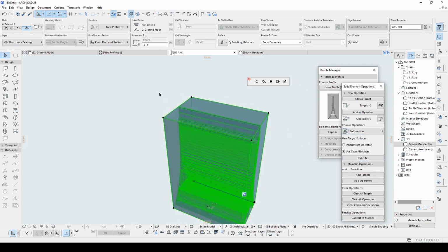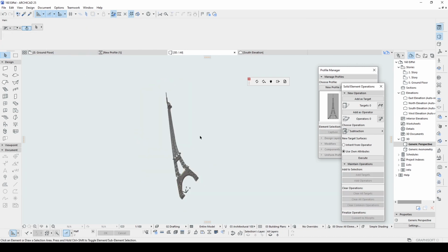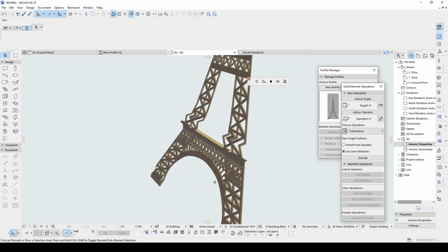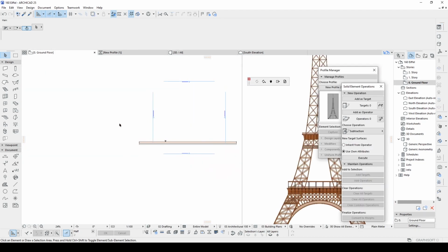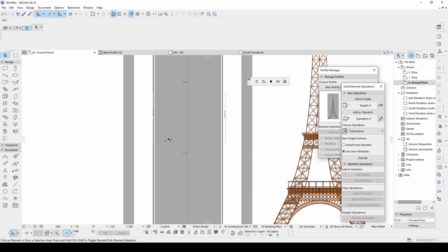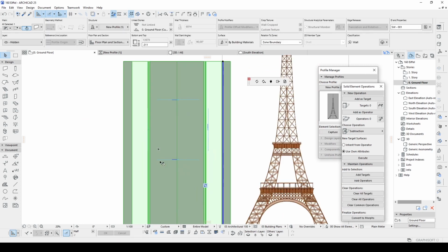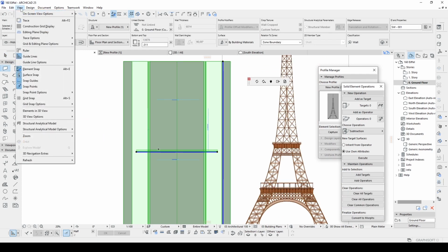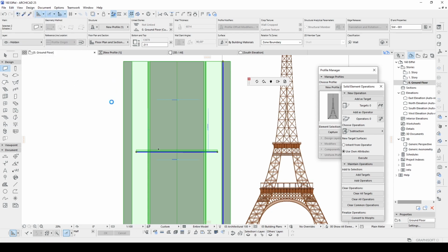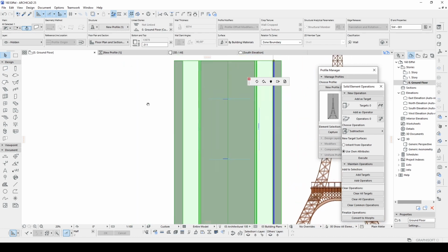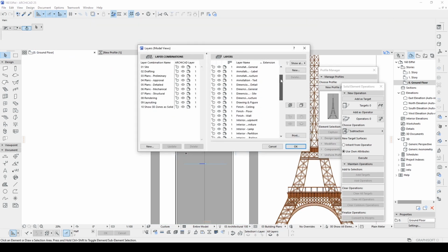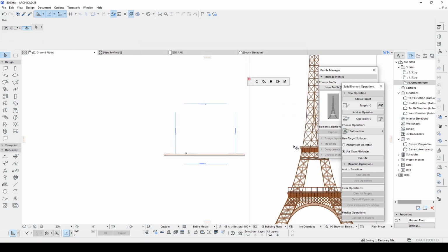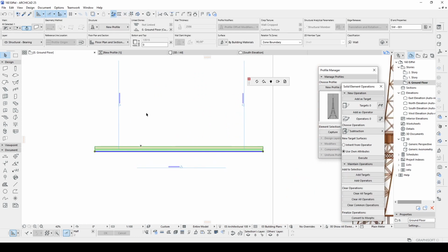Now we can hide this layer, and then we get this shape. Not bad, we can go with that. Let's go back to the ground floor again, and I want to see the hidden layer too. And I want to select all of the walls and make them a group. And then we can hide the void wall. After that, go to layers. You can hit Ctrl+L on your keyboard. And just be sure suspend groups is off, and you just select your wall.